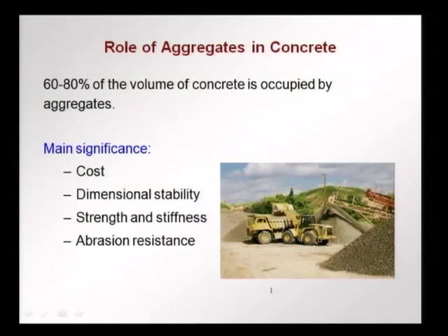Secondly, in most applications the aggregate is stronger than the cement paste. Therefore, we get a stiffer and stronger concrete due to the presence of the aggregates. Lastly, aggregates give abrasion resistance. So, there is less wear and tear, whereas cement paste is more powdery and can be worn off more easily. Aggregates prevent this from occurring.